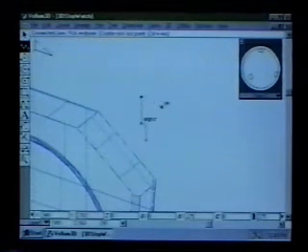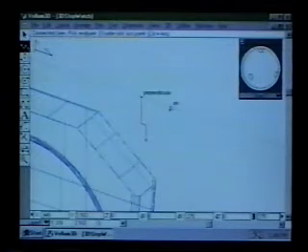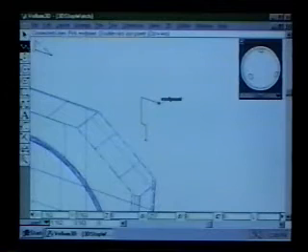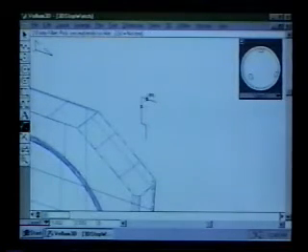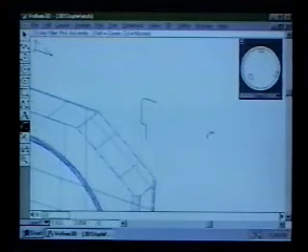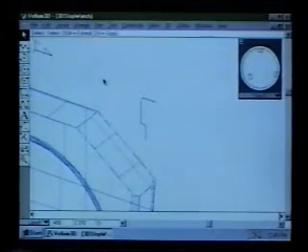And then we'll come across half of the top of the button so that we can rotate or revolve this button about its center. And this distance will be 0.185. Now the button actually has a rounded corner, so we'll go ahead and put a fillet on this that's going to be 0.03. So it'll be a fairly small fillet, but nonetheless it'll be a rounded corner, so it won't be quite so square. And we can actually even zoom into this again.